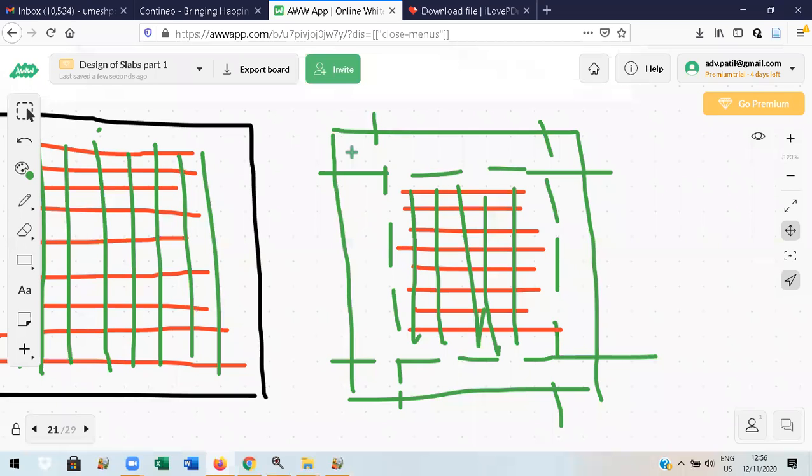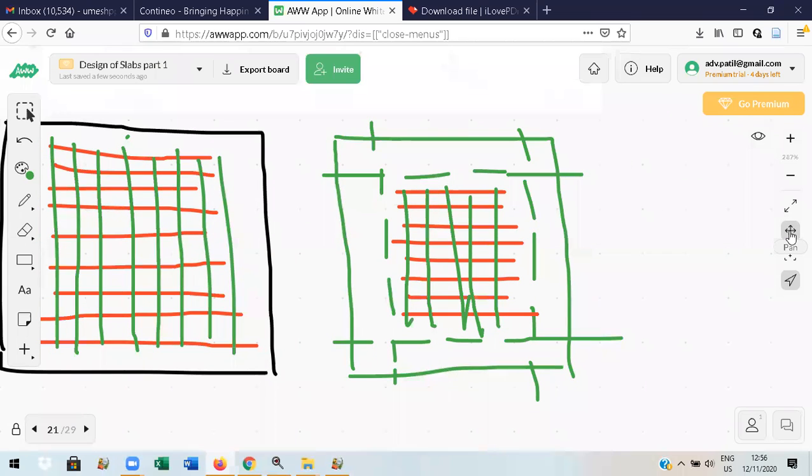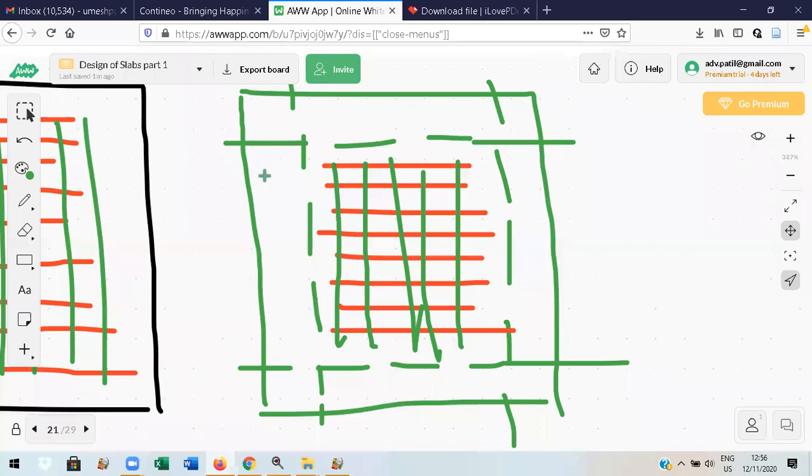It means in the edge strip, all along, there are 4 strips. In this area, we are going to provide only minimum steel. Minimum steel is provided. That calculation I will show you there. So this is how the reinforcement is done theoretically. This is a theoretical diagram.